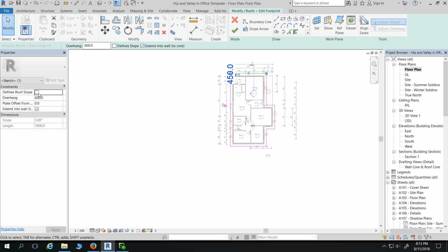It's probably going to be exceeding sometimes. So you're trying to make it skinny? Go back in and edit the footprint, then click on that line. You've got the slope there, and there, so you can just untick it, or just leave it on. Just leave the one at the back. You can do a window select on those as well, and that one too. Okay. That's going to be a steep roof.